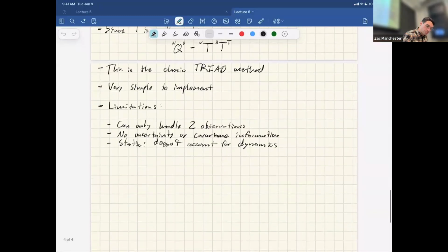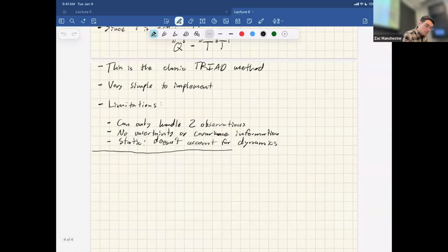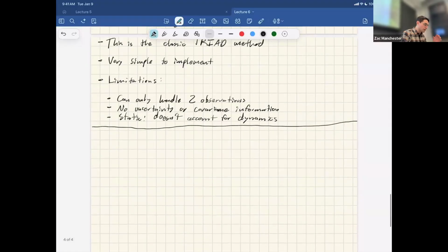So here's what we're going to do now. This is kind of the most basic thing you can talk about. We're going to now start talking about statistics and estimation and all that good stuff, and basically how to do least squares for attitude. Who's done least squares before? Please say everyone has done least squares before. Yes, good. So that works for vectors, right? Now we have to talk about how you generalize that for attitude or for rotations. And the answer is something called Wahba's problem.